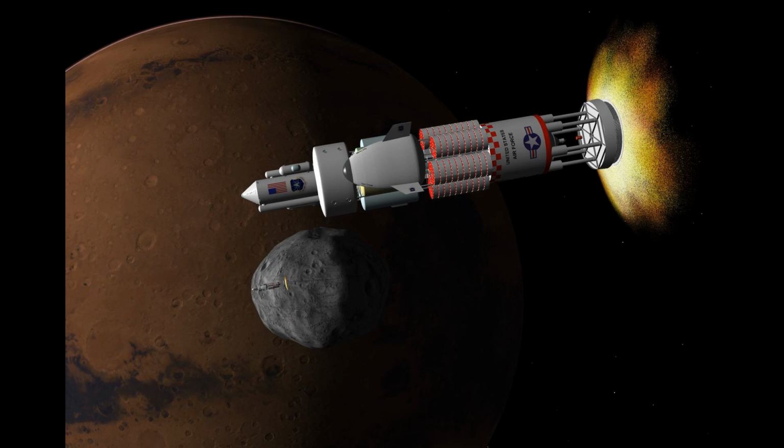Extremely high specific impulse, but extremely difficult to build. You would have a sort of pusher plate that is basically heavily armored, and it would be suspended behind the spacecraft with springs and dampeners so that the short impacts would be converted into a sustained, still kind of varying but no longer shock impact, a sort of varying but sustained propulsion.